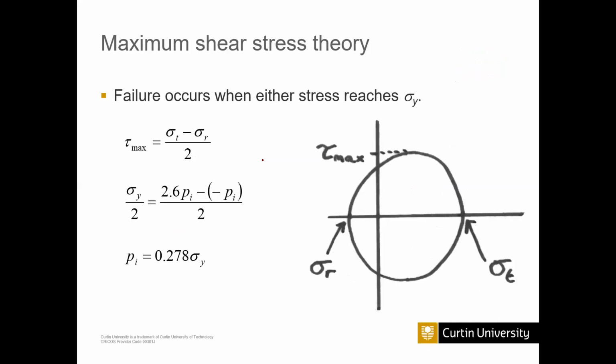So then Tresca theory, maximum shear stress theory. In that theory, there should be a shear stress maximum point you need to consider. So you need to draw the Mohr circle, or you can use the equation if you want, but tau max will be given by, because we already know the two principal stresses, because at that plane there is no shear, the difference between the two divided by 2.